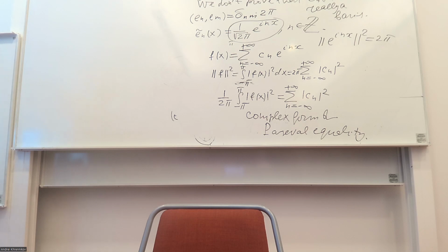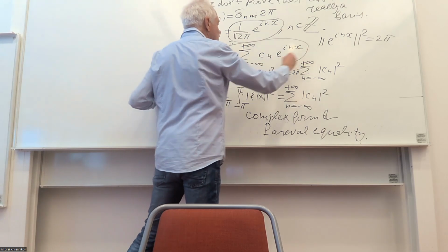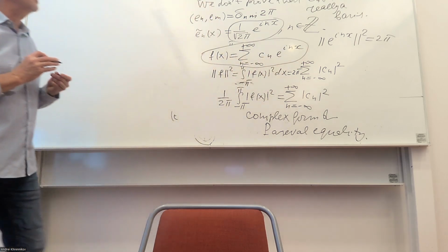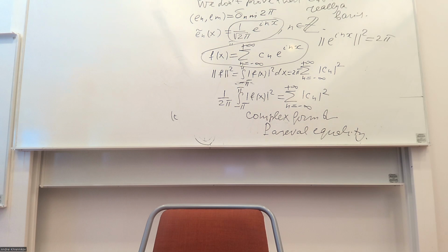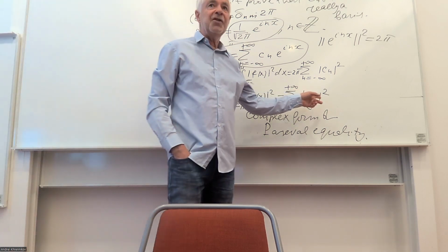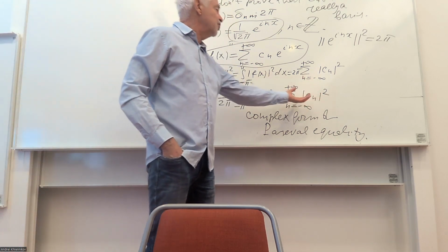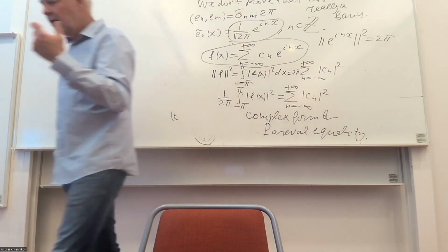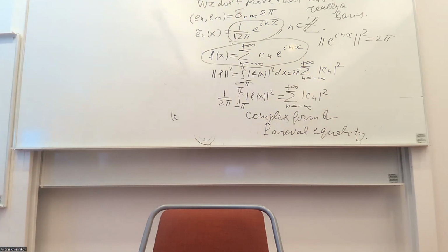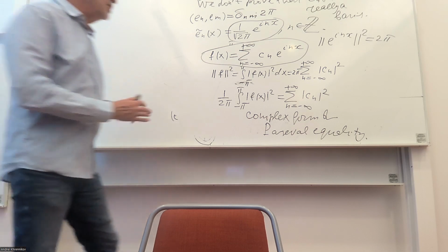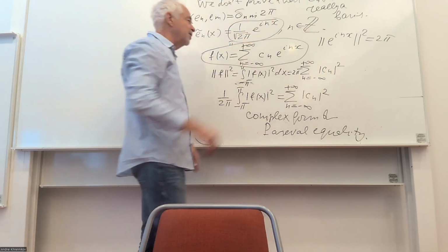And those who work in signal analysis always work with complex amplitudes, and they always use this Fourier expansion, not through cosine and sine, though some use cosine and sine. Sometimes it's better complex, sometimes real. It depends on your problem. Again, these are frequencies, and you select the largest coefficients, and this is more or less where your signal is concentrated. So you cut off everything in this series, and only select those that are big.